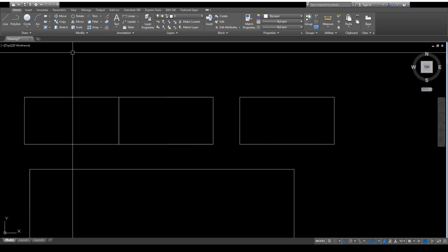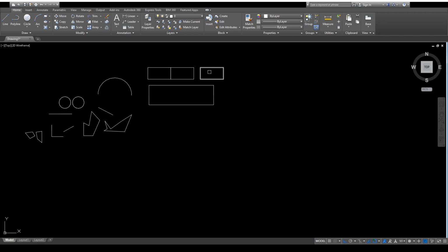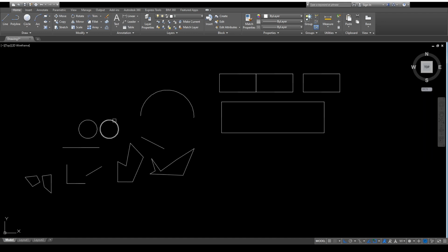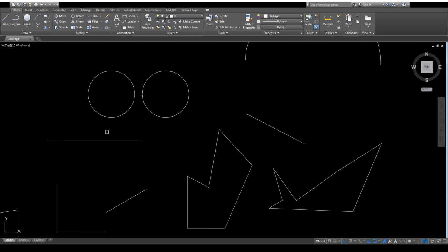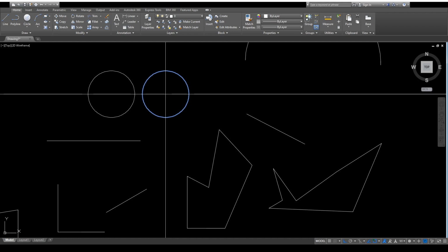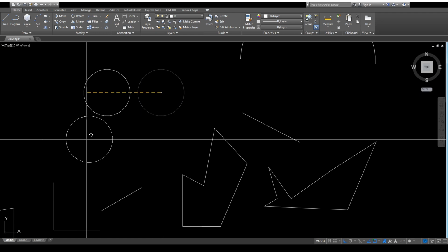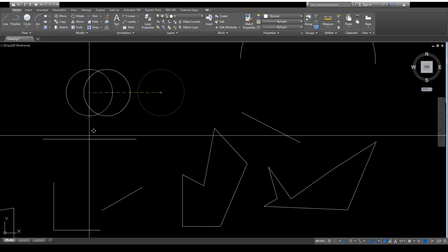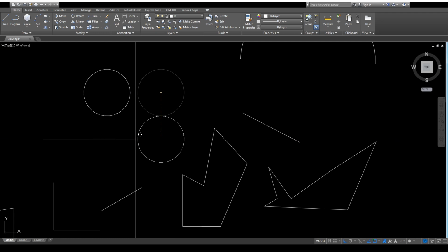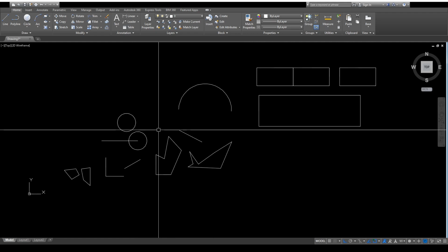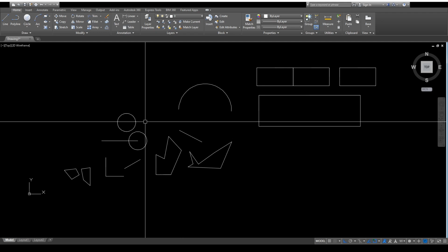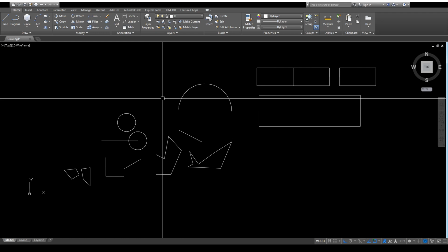So, ulitin ko po. Move command is this one, move. And then, for example, you want to move the circle papunta dito sa linya. Select the circle. And then, kung tapos ka na mag-select, press spacebar. And then, gusto ko siyang hawakan sa gitna. Click. And then, I want it here sa end ng line. Click. Ayun, yun lang. I'm not dragging ha. I'm not click and then hold. Click lang talaga, bitaw, and then galaw ng mouse.